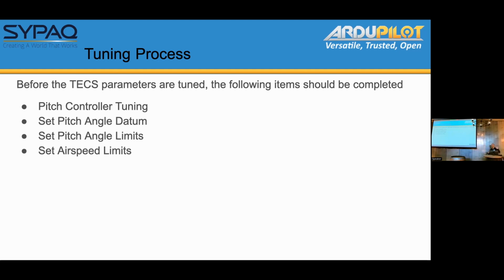So the first thing, and I'm not going to talk about pitch controller tuning much at all, because we've got a wiki for it now. We have an auto tune process for plane users, but start off with tuning the pitch controller. You don't have to go super aggressive on the gains, but it does need to accurately follow the demanded pitch angle, to within about plus or minus a degree in light wind conditions. Then we need to set the pitch angle datum.